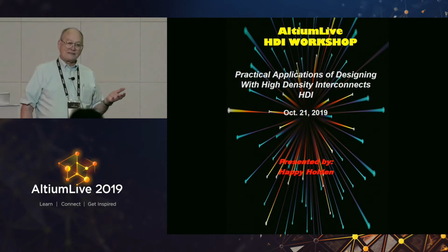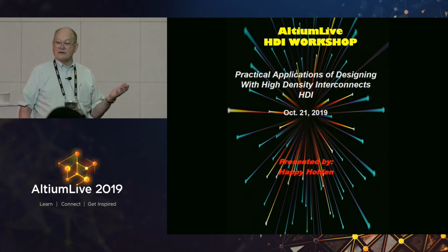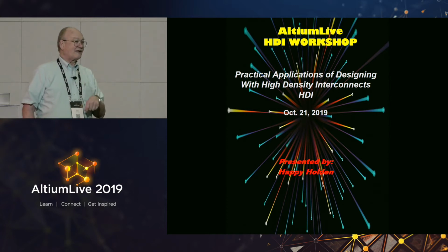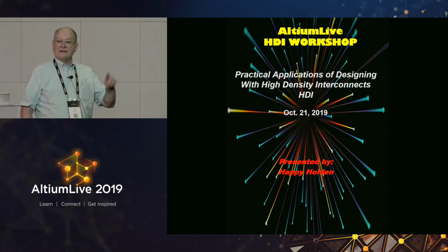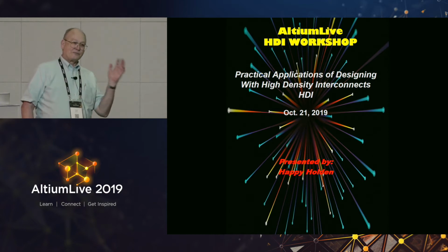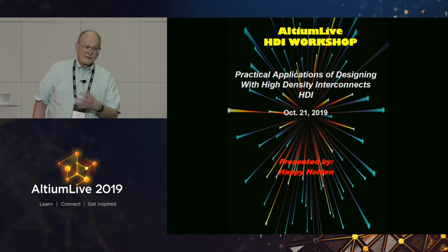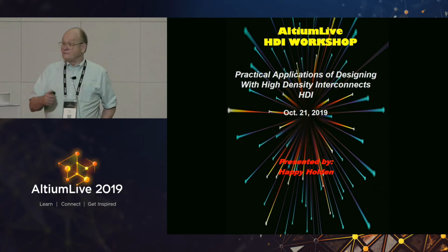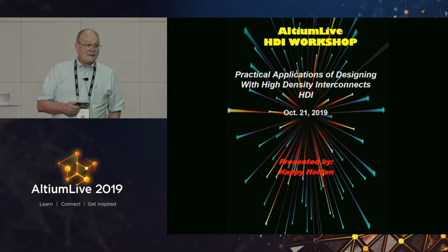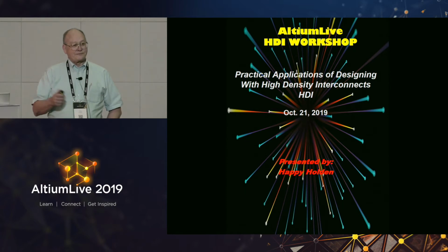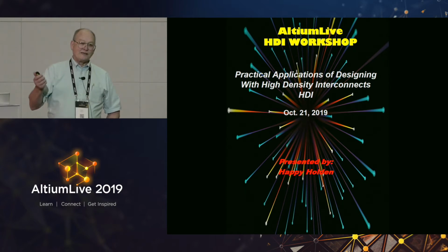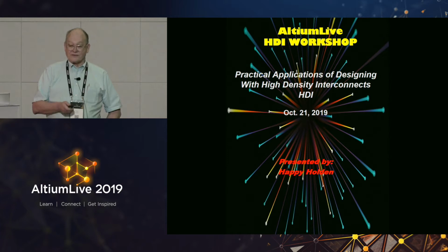But he said, the last chip didn't have that problem. I said, yeah, but the last chip was 200, 300 nanometer transistors. These are 7 nanometer transistors. So look at the specs, the turn on and turn off time. The clock hasn't changed, but your rise time has. And that's one of the reasons why we say that if you're not used to signal integrity problems today, wait a year or two, and then you'll be in the center of a lot of signal integrity problems.